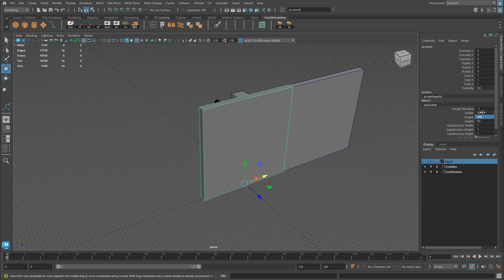You could have smaller values, so you could have maybe 310, 320, but I tend to avoid going that small to start with. I usually stick to whole values and larger numbers. I may go in the 50s, so 350 by 350 could work, all depends. But this early on, I tend to just stay with the whole values, 300, 400, 500. And then I could always add variations in between for half values or something close. But this will ensure that you stay on the grid in Maya as well as on the grid in UE5.